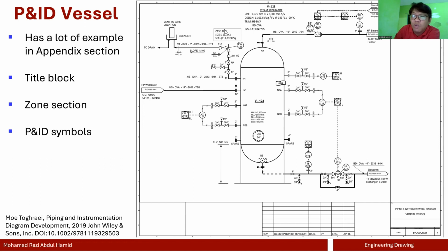There are a lot of cases when people want to design a pressure safety valve. I recommend you to read API 520 or API 521, I don't really remember. So a lot of cases, for example, in the case of choke valve and stuff like that. But the idea here, these are for safety. Insulation, again, they have insulation. This unit will be insulated, so they probably have something like glass wool on the outside.